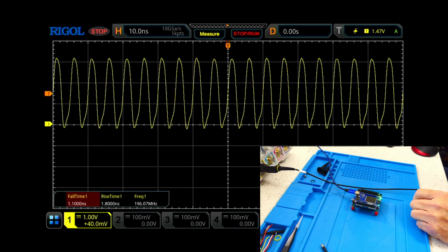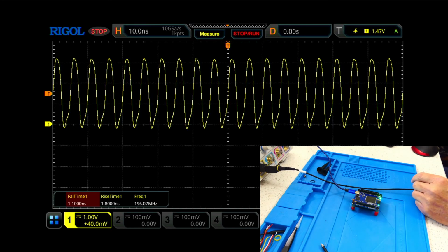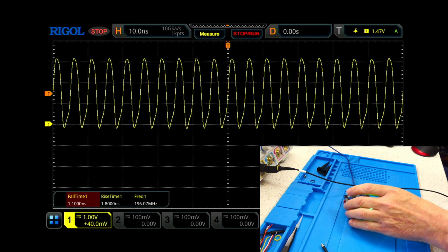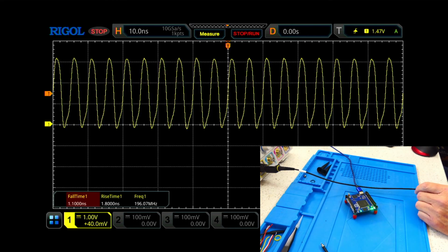Next time I'll make a video showing some progress on my HyperRAM interface. I'm going to make a little menu system and implement a command processor in Verilog, and take advantage of one of the serial ports here to make a UART for the user through PuTTY, let's say, and initialize the HyperRAM, do some memory tests. So that'll be the next video I make. Once I get that done, I'll post it online.